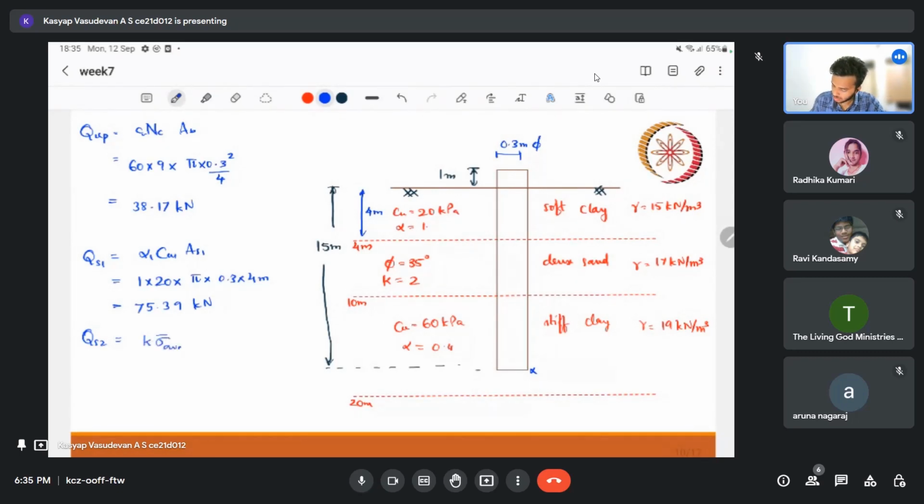And what else do we need? This is the resistance into the area, right? The shearing area will be As2. So what are those values? We need the average, right? The average sigma dash can be written, as in the IS code, also as Pd, for your information.